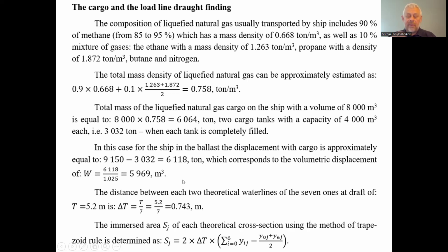Okay, so perhaps we will consider not the fully loaded ship, but partially loaded, only with cargo in just one of the capacities. We have to consider the most dangerous circumstances of the ship loading. The most dangerous can be if the ship has cargo in the aft capacity and the middle capacity for cargo is empty. So in this one definite case there could be the maximal bending moment of the ship on calm water and with ballast, to exclude the slamming factor.